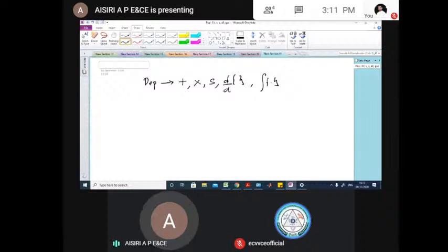If it is an independent variable, then it is time shift, time scaling, and then the reflection. It has a certain order in which it has to be done. First you have to do the shift, then the scaling, then possibly the reflection. It is the same order in which it has to be performed. So these are the operations on signals. It could be on dependent and independent variables.